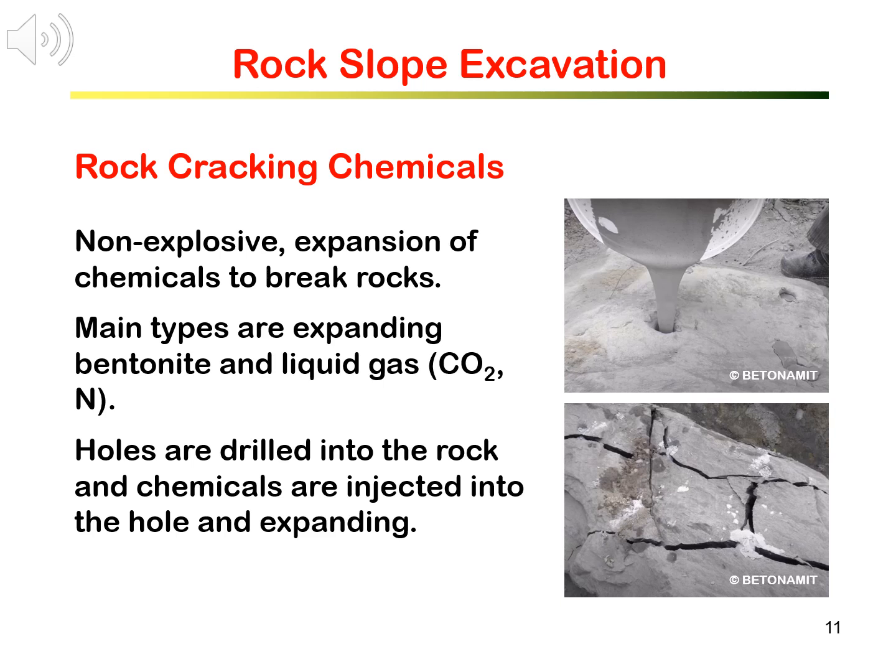Liquid gas is primarily liquefied carbon dioxide, CO2, and sometimes nitrogen. When liquid gas is injected into the drill holes, the liquid turns into gas with a quick change of volume. The pressure from the gas pushes the hole to open and cracks and fractures the rock.